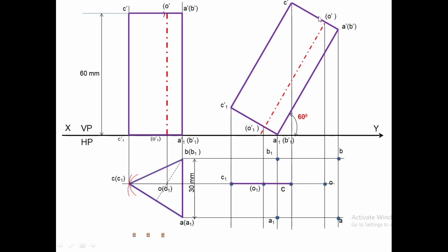The top triangular face ABC is seen. Mark ABCA in sequence. Mark the boundaries. This is the boundary by a thick line, like this. You got the remaining edge A1B1, which is at the inside, therefore you show it by a dotted line.